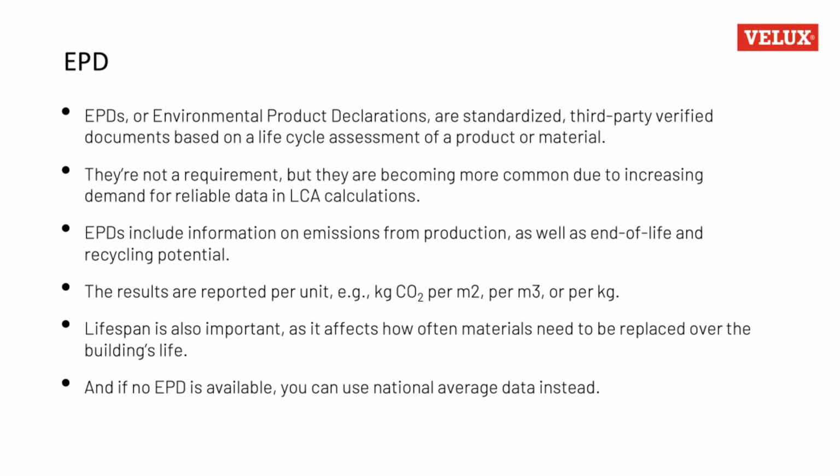For example, if you have an EPD of insulation, you would maybe have a declared unit of cubic meter, and then the result would come out in kilograms CO2 per cubic meter. And that's what we use in the LCA. Then most EPDs also have a lifespan for the product, which is important for when you have to replace the materials during the lifespan of the building. So lifespan can both be materials and building components. So it could be a window or a door, but it could also be a material, a roofing material or a facade material. Yeah, exactly.